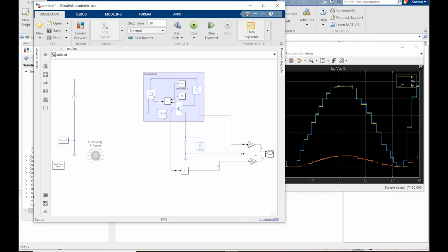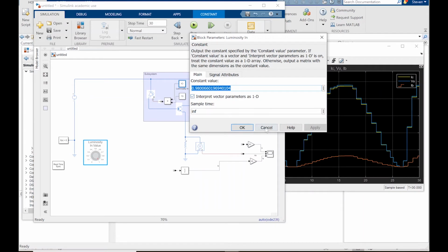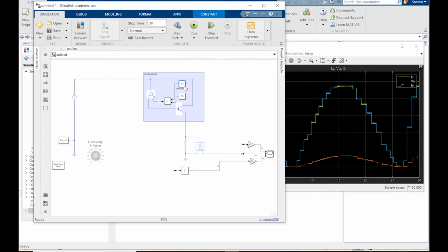So I'm going to go here and delete what I really don't want. All these sensors are just to go through the modeling process and to make sure that my circuit's going to work the way I want. So now I don't need them. I'm going through and deleting the voltage and current sensor. If you want, you could keep the current sensor and have a 4-component part. If you want to measure the current to the base, you could do that. But essentially, what we just want is a working component.